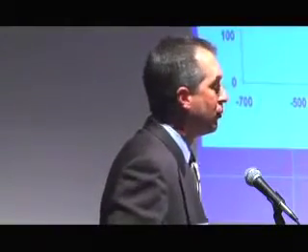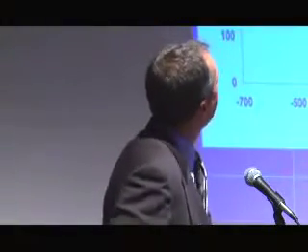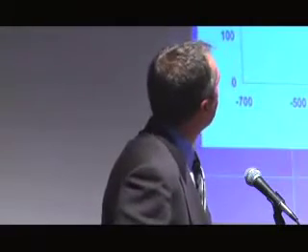One of the things someone came up with was, well, what if you vibrate it by putting sound waves down the column of the wet cement as it's gelling? And so it actually works. It's just one technique that tries to give us a better well. It reduces costs. It costs very little to do that, but it's just people using their minds trying to figure out better ways to solve some of these problems that are everyday production problems. Ultimately it will lead to more production out of that well, and certainly less cost.